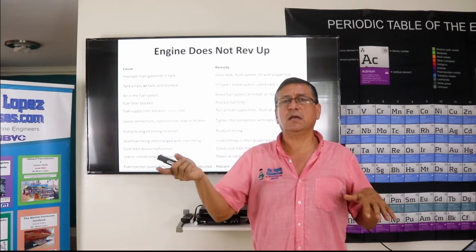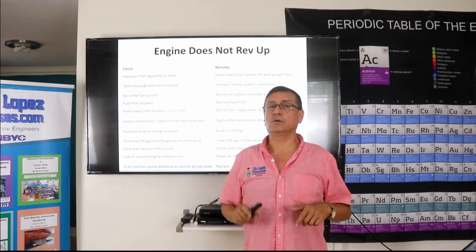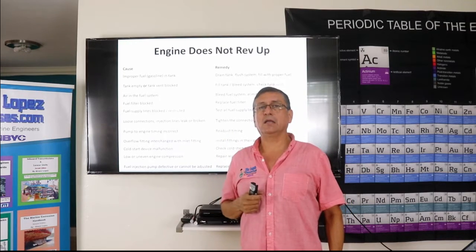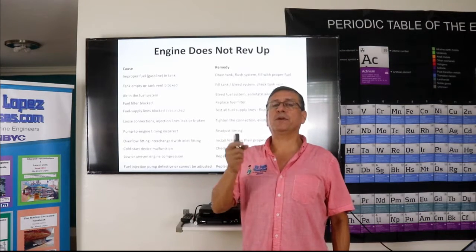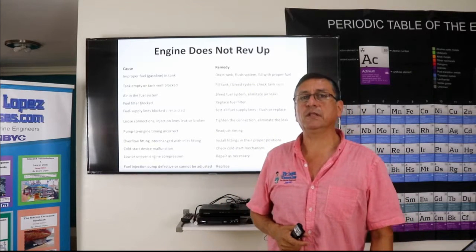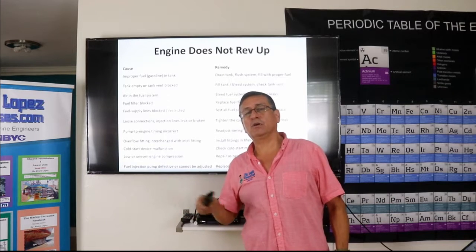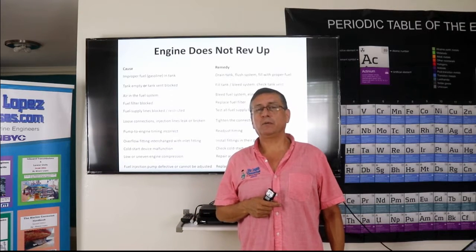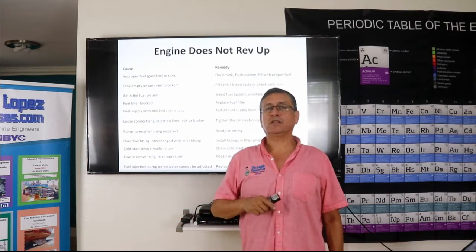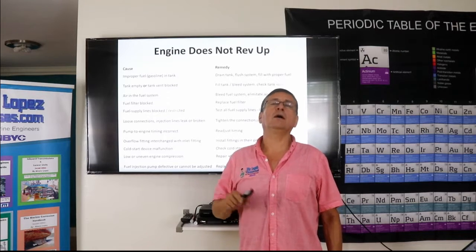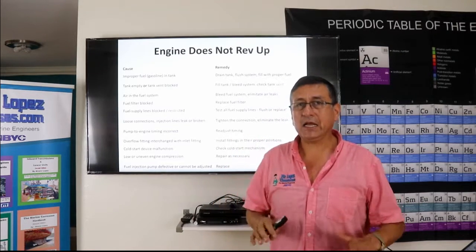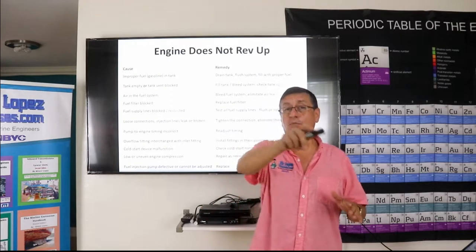What about the pressure on the common rail? Perfect. What about the pressure on the filters, in the secondary filter, low pressure side? Oh, perfect. What about the bubbles on the Racor Parker filter? No bubbles? Perfect. Do you have water in the water separator filter? No, I don't have. Okay. Those questions are critical in order to identify other important questions.